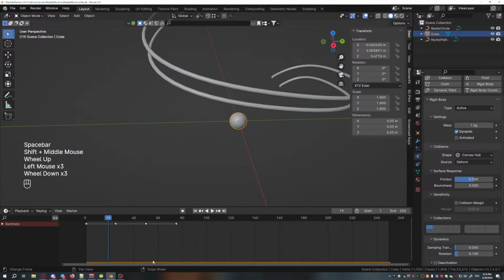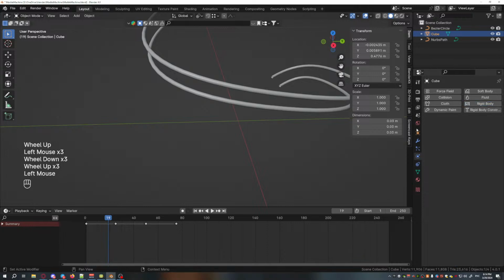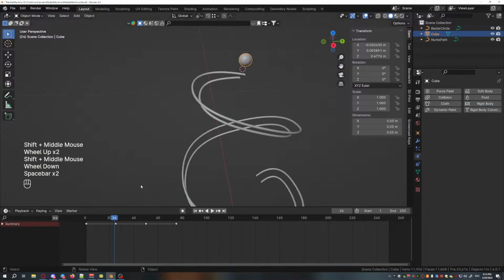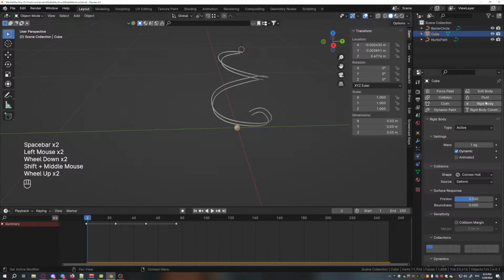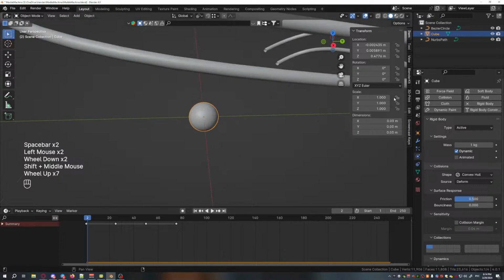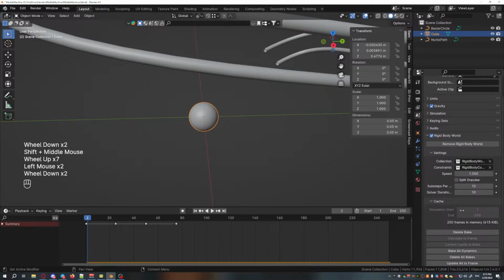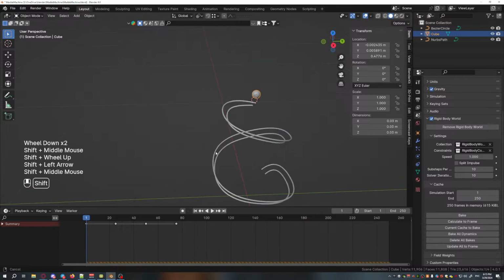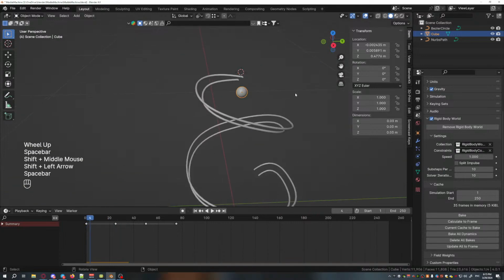I see that there is baked information there. It teleports straight to the 0, 0 coordinate when I add the rigid body. Yeah, I think that I can delete baked information, and now we're talking.